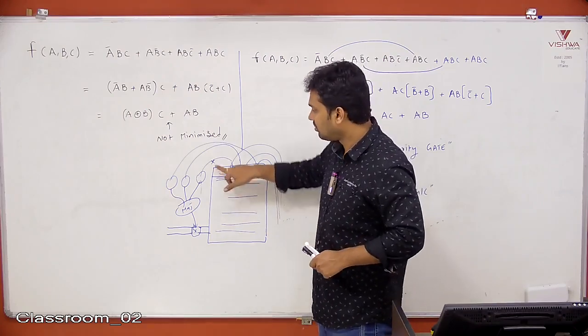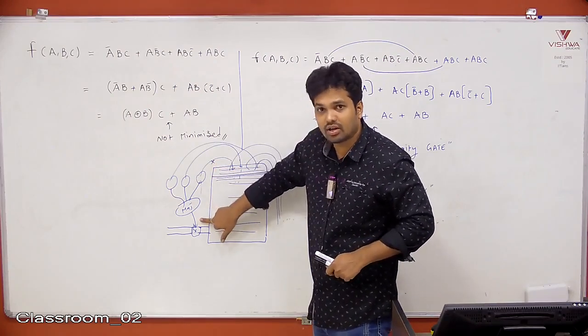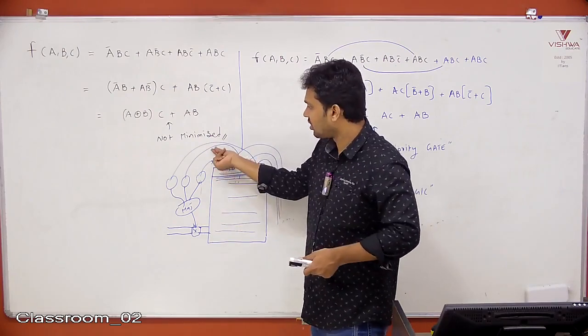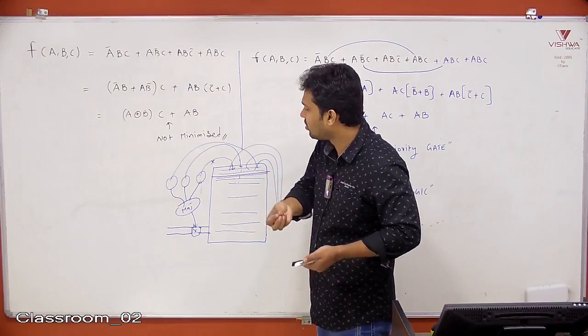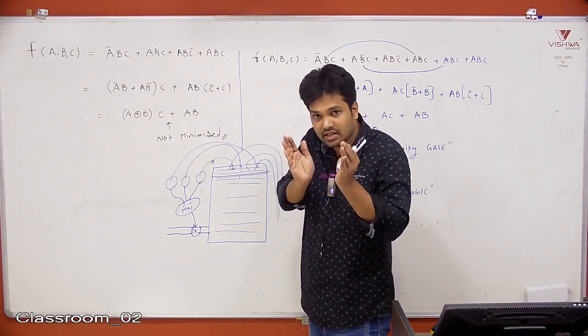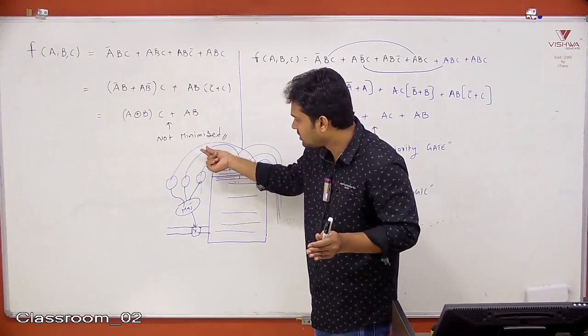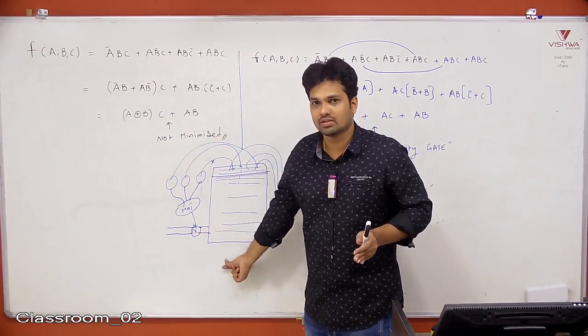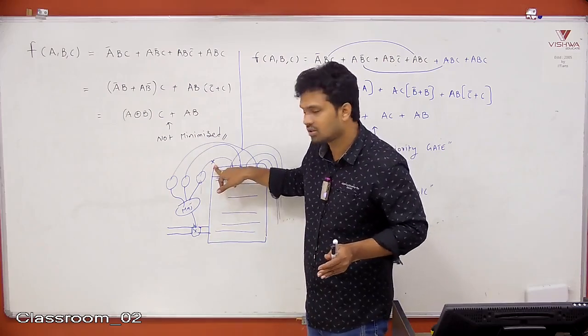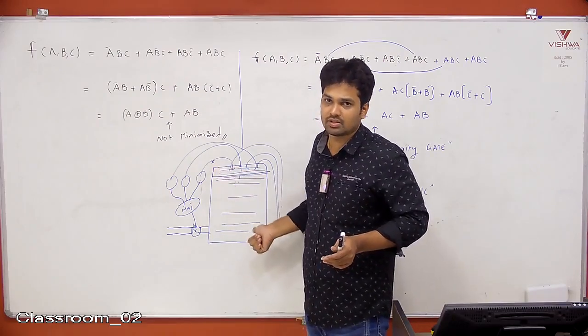So, 1 may go fault also, still it will work. If 2 go fault, we cannot do anything. But out of the 3, the assumption is 1 may go wrong at any time. Still, majority of the 3, 2 are saying 1, so take it as 1. 2 are saying 0, take it as 0. This can minimize the chance of fault compared to the previous case.